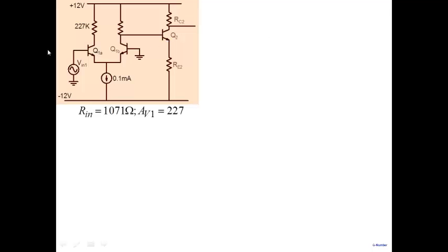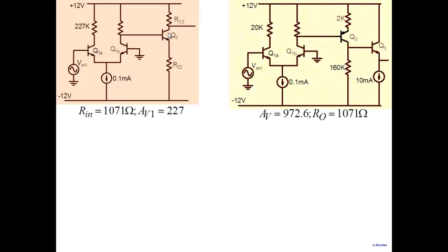So then what we had said was, don't look at an NPN gain stage, look at a PNP gain stage here. And to complete the op-amp, we had said that you have to add a common collector amplifier to provide the lower output resistance. So that was a very simple op-amp. What we had seen was that if you design this differential pair with the maximum possible gain, and then you look at the design of this common emitter amplifier, you find that again you don't get any gain.